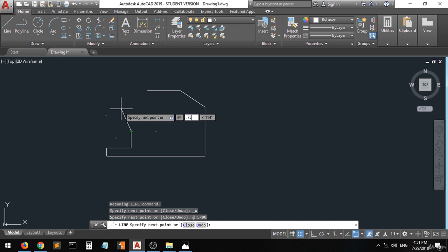We'll do it at 0.75. We don't have to enter the minus, because when you enter the minus, let's do it, I'll show you how it works. Minus 0.75 in the angle of 180, enter. See, the negative sign will flip the line, since we have to put it positive from here to here, but it was flipped since we entered the minus.